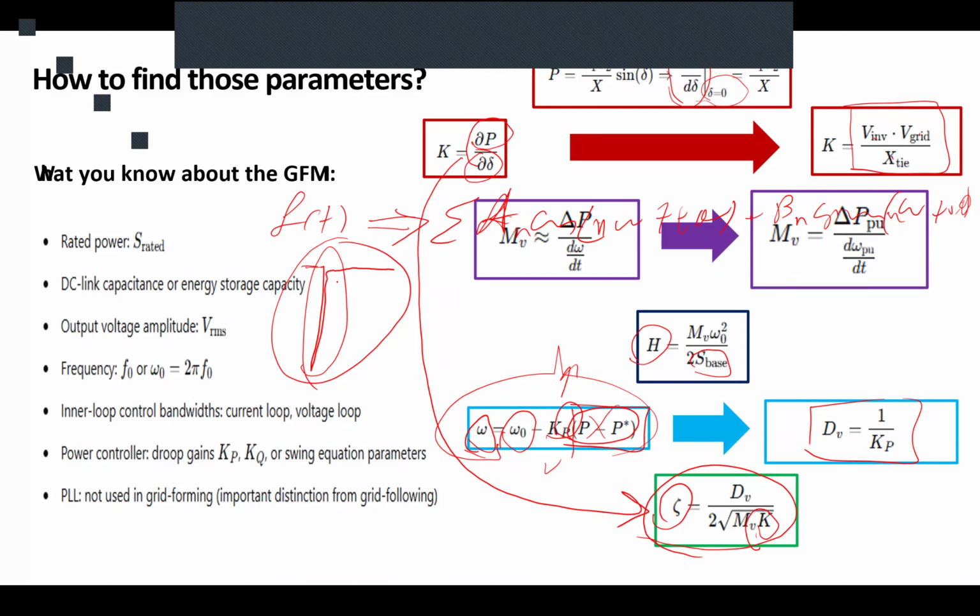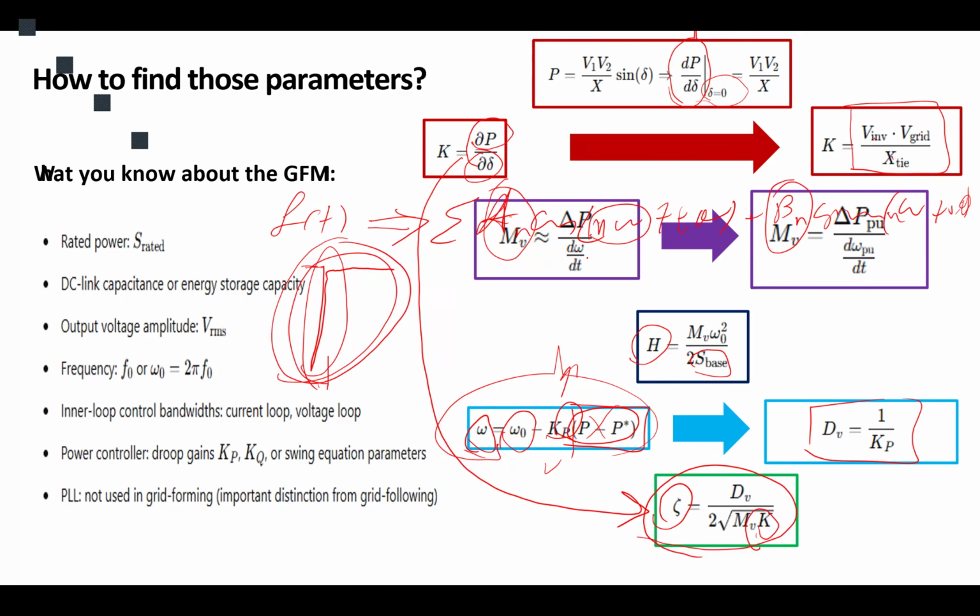What would happen in the Fourier series of this time function is that most of the values you see in an and bn are related to very high frequencies. This is the mistake they make when they define a transient disturbance as a high frequency effect. Because in the Fourier series of those disturbances, you would see more higher frequency than lower frequency.